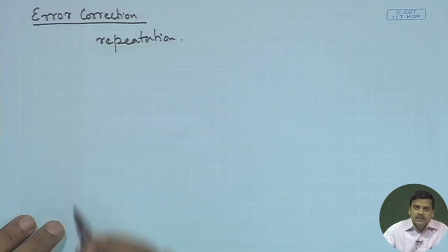It could be that some particular word was sent, the receiver did not make any meaning out of it, and asked for a retransmission. Now, if the receiver made some logical meaning out of it, although it is not the same word, you would encounter the situation where the receiver is making an error which it is unaware of. So, those things are also part of it. There could be repetition coding. Repetition coding means that instead of sending A, it will send A 3 times. Majority decision rules at the receiver could be used: if 2 out of 3 are of the same symbol, then you would go by that particular symbol.